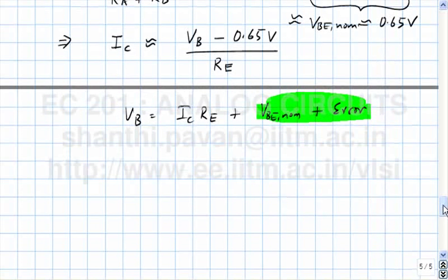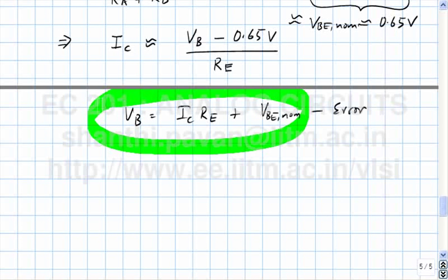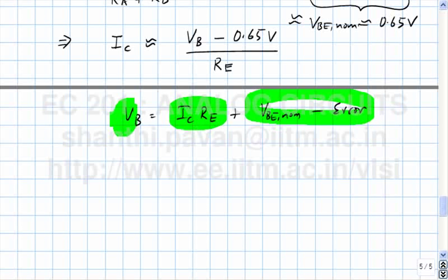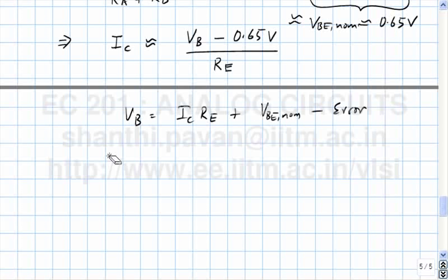So when will the IC you compute using only this part of the equation be close to the true IC? When the error is very, very small. And that is very easily satisfied provided this is a constant. If this potential is much, much larger than this guy, then any error you make here will hardly reflect in IC RE. Does that make sense?